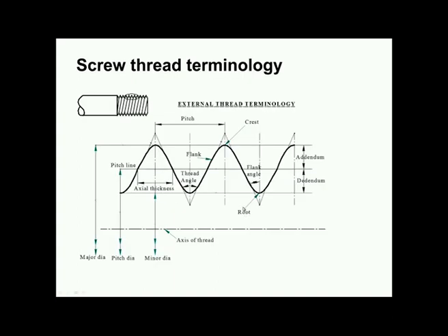Now, let us move to the screw thread terminologies. Various terms are used with respect to screw threads, internal screw threads as well as external screw threads. Now, this picture shows some of the terminologies. You can see the profile of the screw thread and the distance between one point on the screw thread to the corresponding point on the next thread. This is known as pitch,